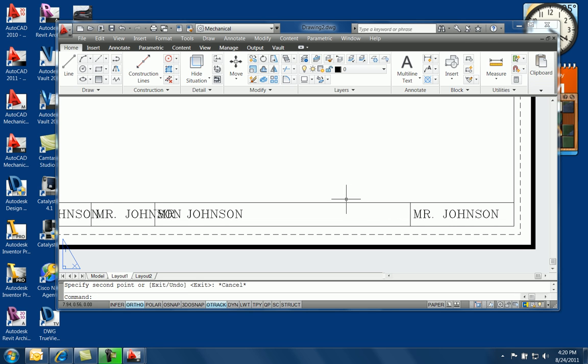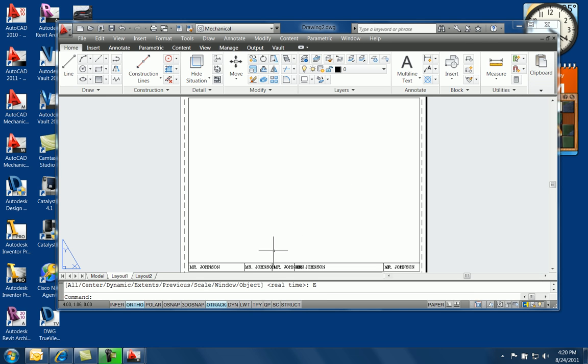Now we're going to change the text. To change the text, you double click, and we'll make it the date. Double click on this one, make it the class, whatever class it is, and double click on this one and make it the problem, 1-1. Click, hit escape, double click on this. We're going to call this scale, semicolon, 1, semicolon, 1.